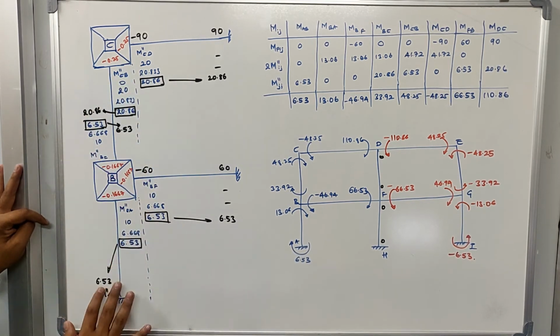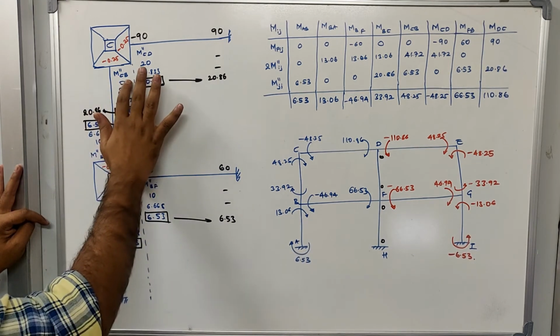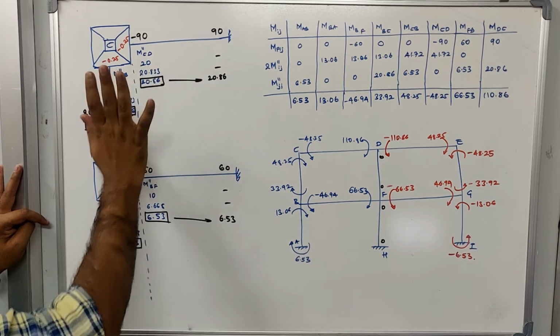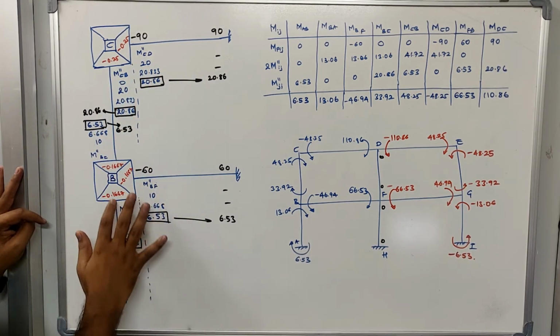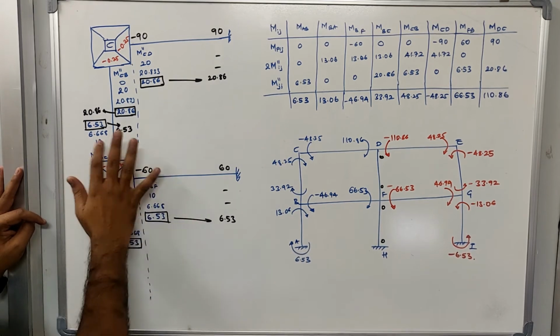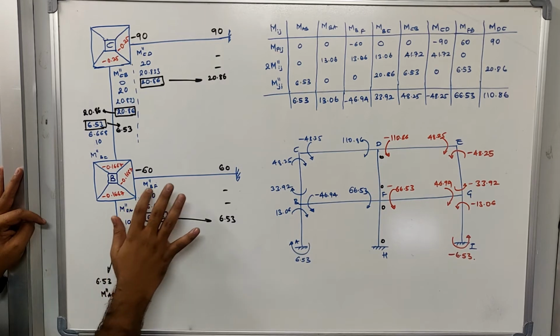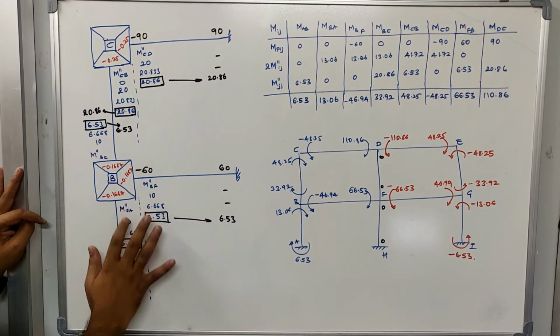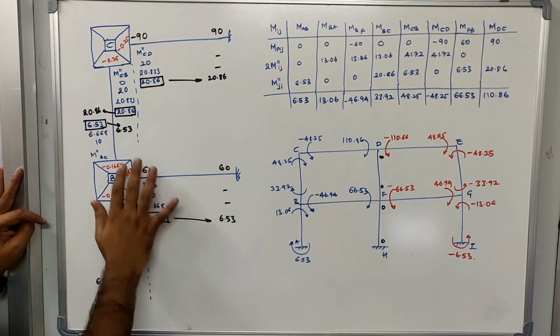As we know, this is already equal to 0 because this is a fixed end. So on the other side we'll assume M double dash CB to be 0. So minus 60 plus 0, multiplied by the respective rotation factors. I'll write down the values here. I have written down M double dash BA, BF, BC, which is 10, 10, 10. Now this completes the calculation of the rotation moment for joint B.